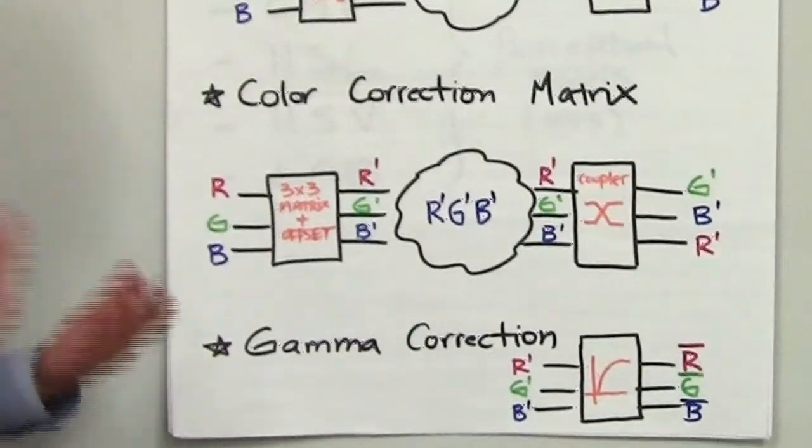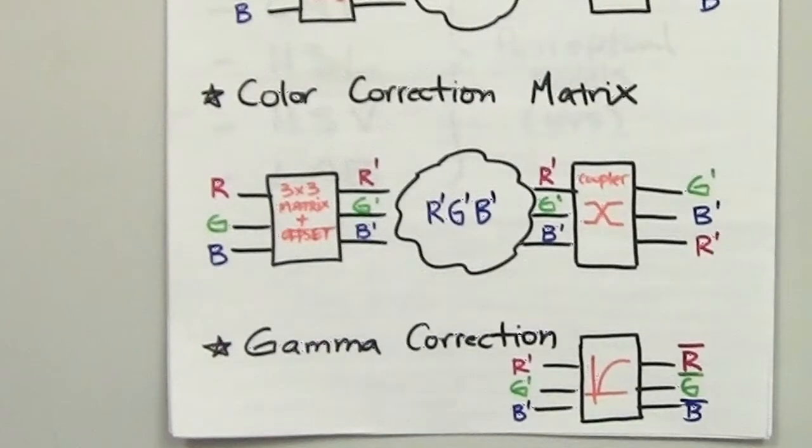We're not going to go into the details of what gamma correction is here, but suffice it to say that in addition to our human visual system being sensitive to frequencies and ranges, we're also very sensitive to dynamic range. Gamma correction is an operation that can resemble the response of the human eye. So for instance, in a display, instead of displaying RGB information linearly, it can be displayed non-linearly to approach the sensitivity of the human eye and match it to computer monitors.